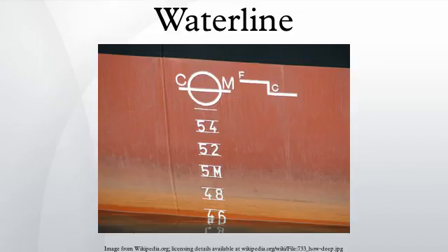Subdivision load line marks: passenger ships having spaces which are adapted for the accommodation of passengers and the carriage of cargo alternatively may have one or more additional load line marks corresponding to the subdivision drafts approved for the alternative conditions. These marks show P1 for the principal passenger condition, and P2, P3, etc., for the alternative conditions. However, in no case shall any subdivision load line mark be placed above the deepest load line in salt water.